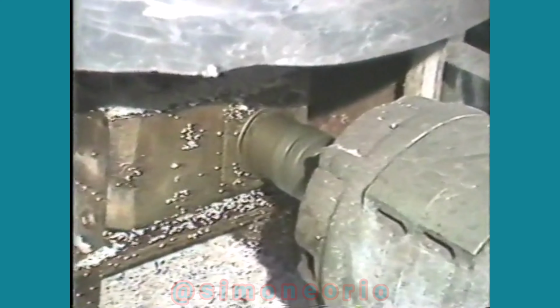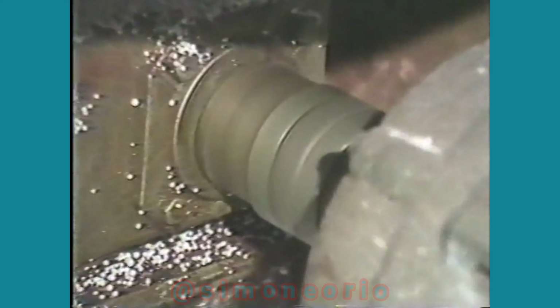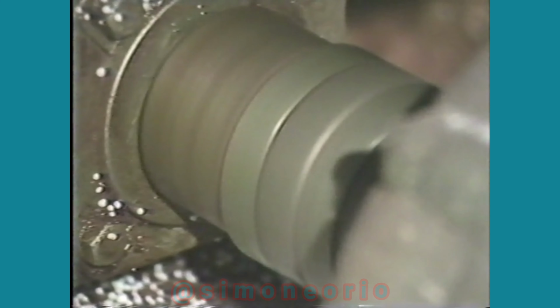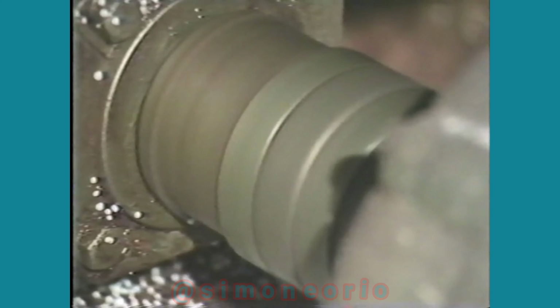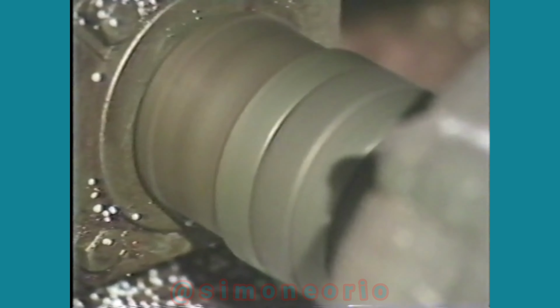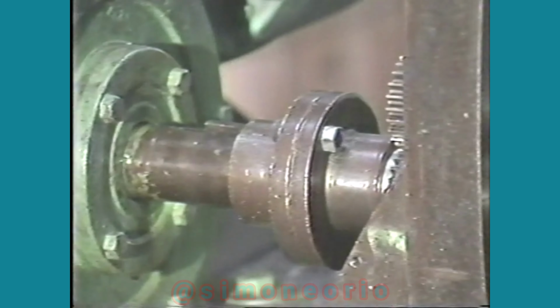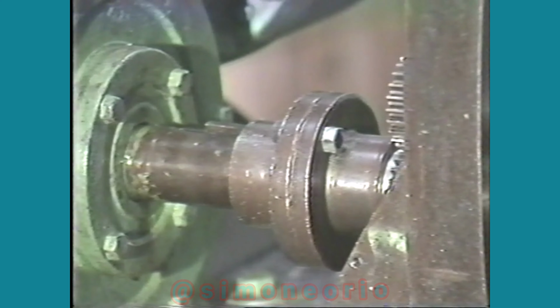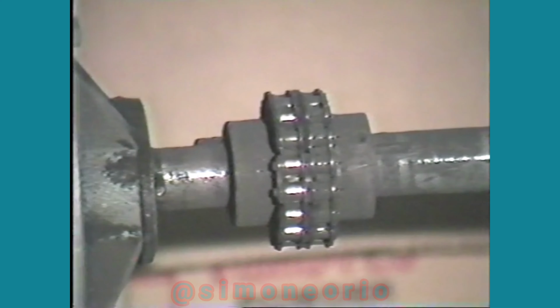A review of this program indicates the following facts. The primary functions of shaft couplings are to transmit rotary power and to connect two shafts. Rigid couplings accomplish these functions, but proper shaft alignment is critical. Flexible couplings transmit torque and connect two shafts. In addition, they offer some misalignment capability. It's important that shafts be aligned properly for any type of shaft coupling.